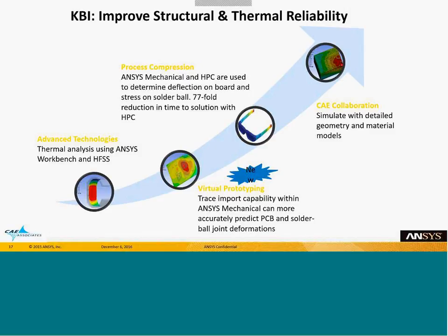Some people may be very sweaty. Some people may be very fit, so perhaps they have a very muscular arm. Or we're using these Fitbits and smartwatches so that we can start to drop some weight, so we have more fat layers than most, right? So each of those is a boundary condition. Each of those scenarios changes your field pattern and how much is penetrating. And so the folks that are creating this smartwatch need to know this stuff. They need to know what will happen if there's a lot of sweat, if there's a lot of water absorption, if there are a lot of different body fluids that are being passed.